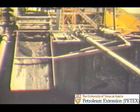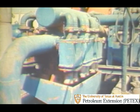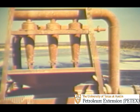A fine screen shale shaker picks up solids from the mud as drilling progresses, and a desilter plus a desander remove more solids. The desander removes the largest of the solids missed by the shaker. The desilter removes even more of the smaller size particles.